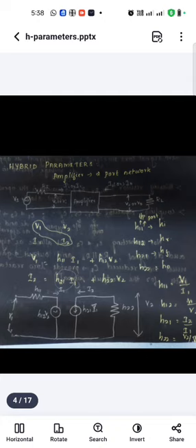Next, continuously draw the resistor, because see the current voltage equation, v1 is equal to h11 into I1, right? The h11 is the resistor. We place that resistor there. Through the resistor, the I1 current is passed. Then in series with that we indicate a plus, and in series h12 into v2. What is h12 into v2? It's the reverse voltage gain. Reverse voltage, which voltage? Output voltage. That's why h12 into v2. Now we have completed the input side.